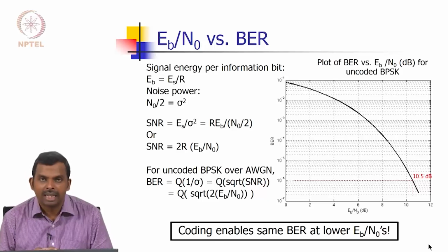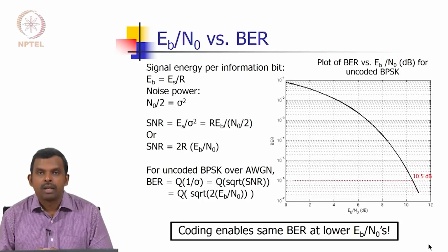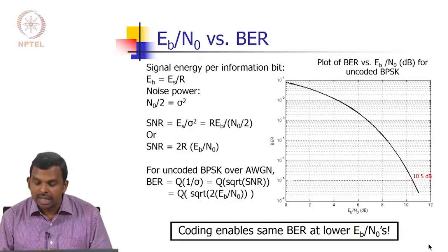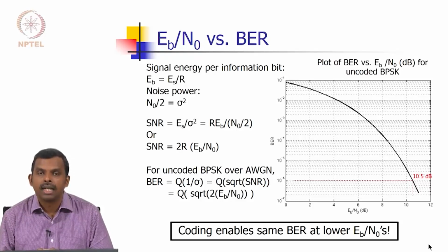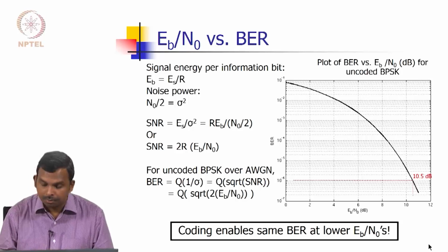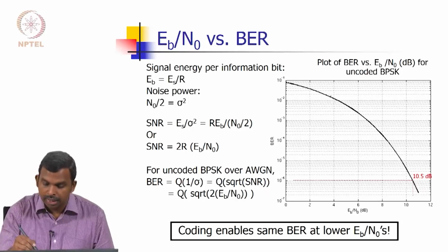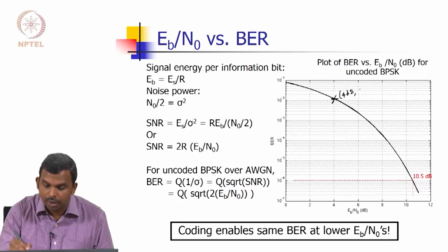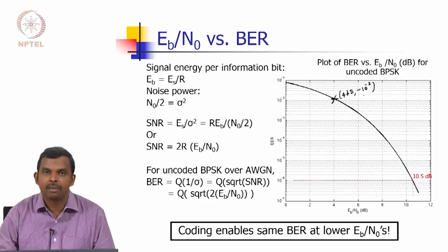Okay. So, to begin with that, in this lecture we are going to see a couple of things. One mainly is how to generate this graph. We will see that using MATLAB and Octave as well, and then how to write a quick simulation to validate this graph. So, this graph for instance predicts at 4 dB of Eb over N naught a bit error rate of roughly around 10 power minus 2, right. So, how to validate this point? How do you validate it by simulation?